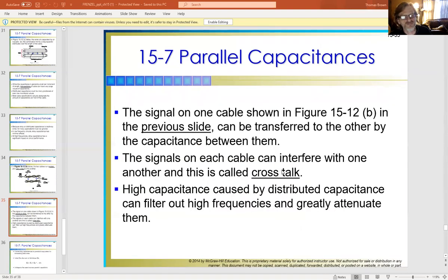In fact, one of the things in residential, it's a code thing. All media cables, like cable lines or telephone lines running through your house, have to be 48 inches away if you're going to run them parallel. Let's say I've got my AC lines running up to the crawl space at the top, snaking down the middle of the house.